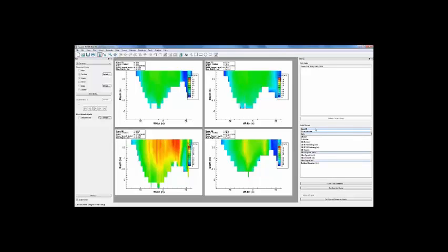Another thing that comes to mind with these cross-section data is velocity indexing. I mentioned earlier that we want a site where we're very confident that when I measure some small portion of this cross-section, it's going to have a constant relation to the mean velocity in the cross-section.